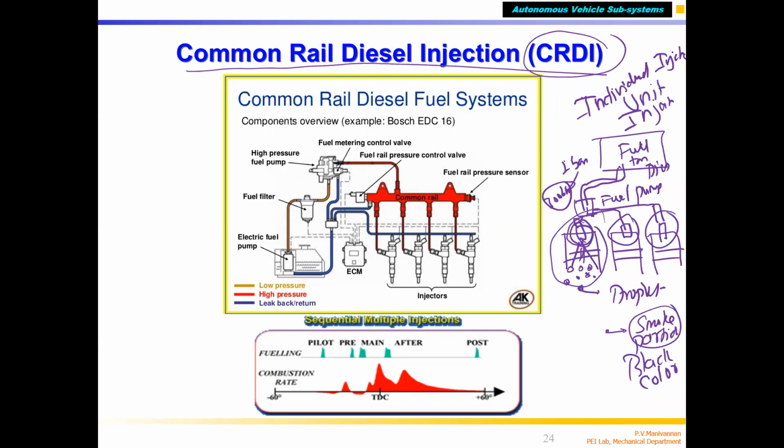Because it evaporates, even the unburned fuel comes out in gaseous form, which is called hydrocarbons. It comes in vapor form only in a petrol engine. But in a diesel engine, unburned fuel comes out as particulates, smoke particles. That means the diesel fuel is burned partially; the core has not burned, because you have a droplet whose top layers evaporate during the combustion process.